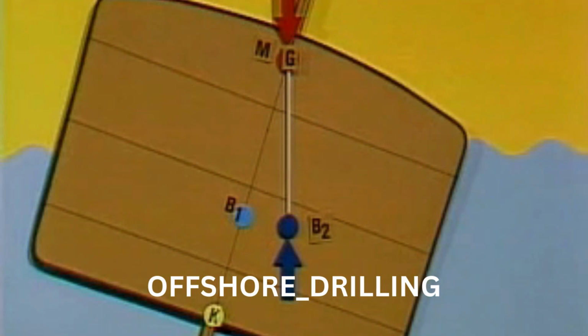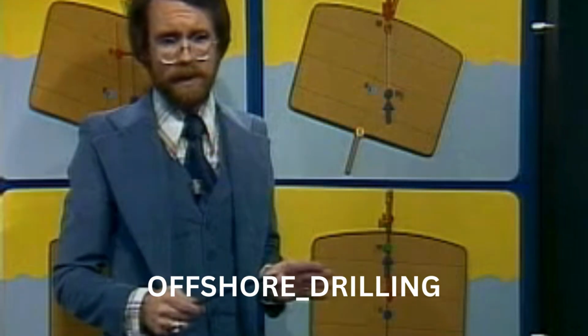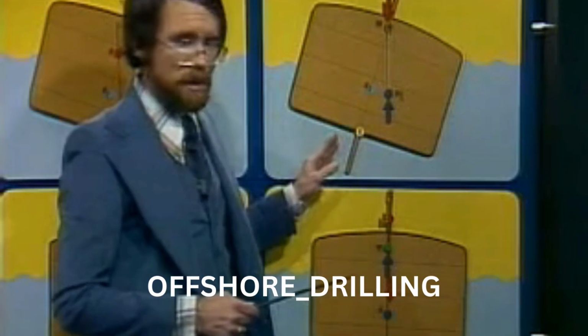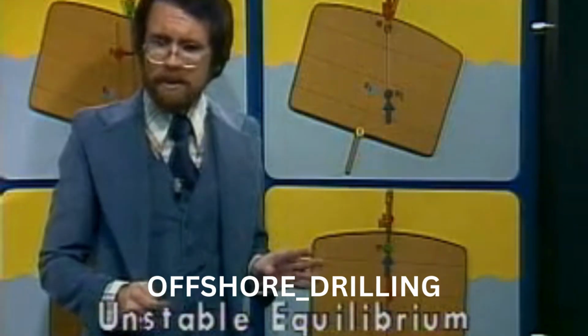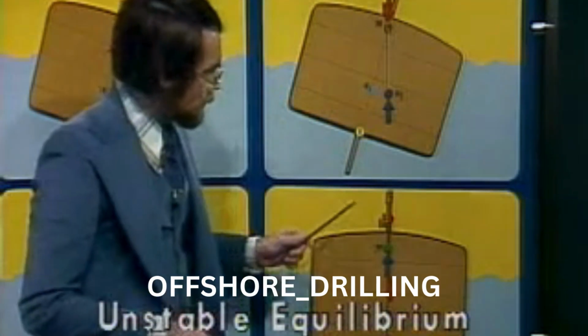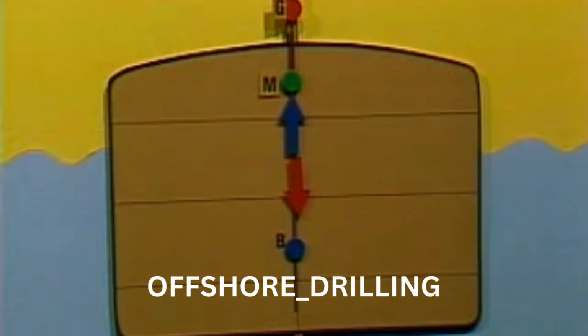There is also no tendency for the vessel to tilt any further. Unless another outside force is exerted on the vessel, it will remain in this heeled position. Finally, we have unstable equilibrium, where G is higher than M. Here, there is an upsetting arm, and the vessel will have a tendency to continue to tilt.